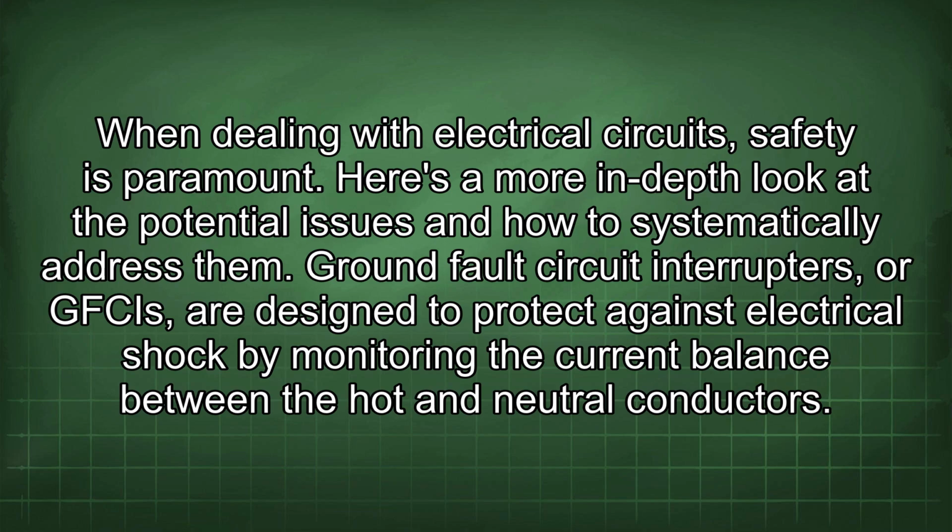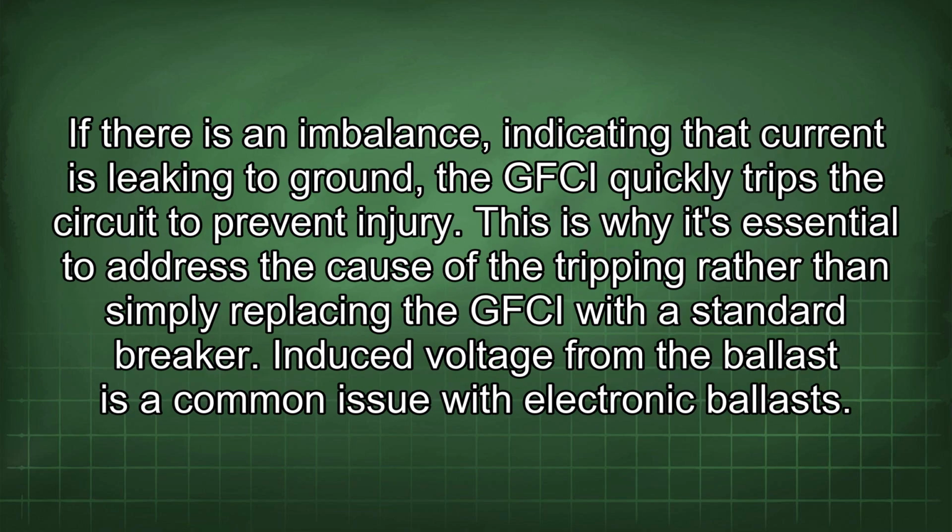Ground fault circuit interrupters, or GFCIs, are designed to protect against electrical shock by monitoring the current balance between the hot and neutral conductors. If there is an imbalance, indicating that current is leaking to ground, the GFCI quickly trips the circuit to prevent injury. This is why it's essential to address the cause of the tripping rather than simply replacing the GFCI with a standard breaker.